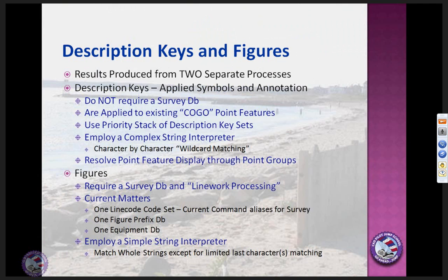So description keys and figures, a couple of things. One, it's two completely separate processes. It doesn't look like it, and it didn't used to be, but in Civil 3D, it really is two separate processes. Description keys don't require a survey database. They can apply to any point feature that exists, and they can be reapplied. I can change my current description key and reapply it to any point groups I want.